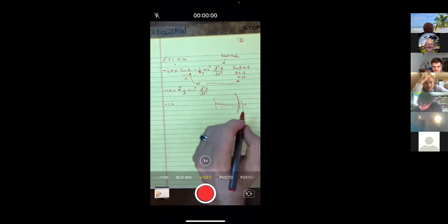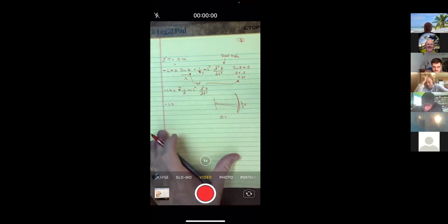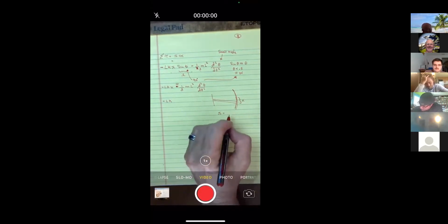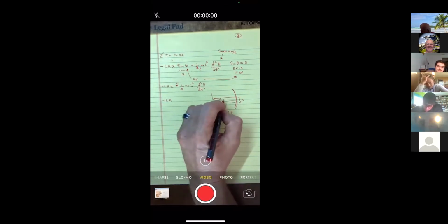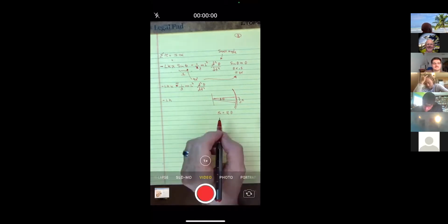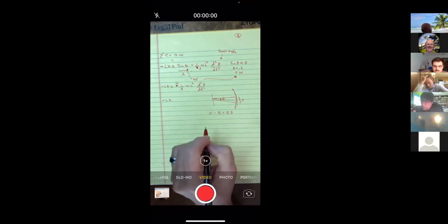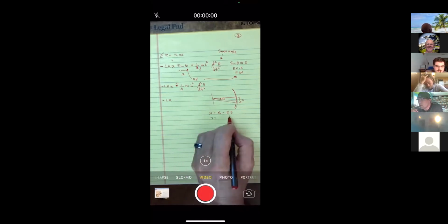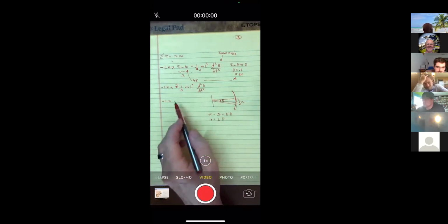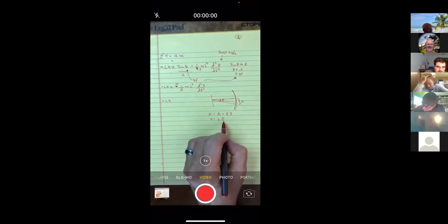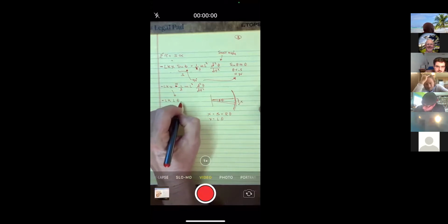But if you remember from your math class, usually an arc length we called an s. Oh, and I guess you also did this in Physics 121. The arc length is the radius times this angle, and that would be that pivot angle. So if I call that pivot angle theta, which I have been, then this arc length is this s, which is pretty close to that x. And the r is the length of the plank. So I would say that x is the length of the plank times the angle. So I'm going to put in place of x, L theta.